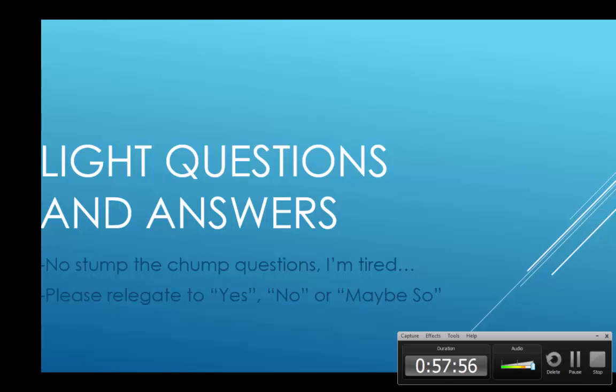One of the things that I see happen frequently is that people will use a design table or configurations at an assembly, and then they will try to control the length of a part. And you can, and it kind of works, but it doesn't work very well. Usually what happens there is that you can control dimensions and suppression states at the assembly level. It works out great for that, for all assembly features and stuff like that.